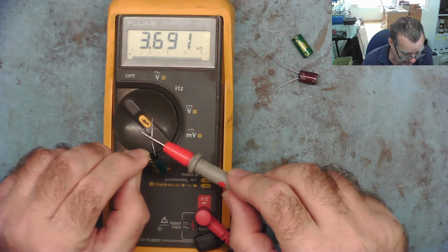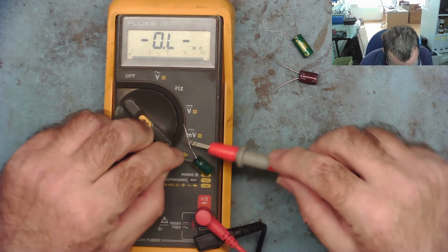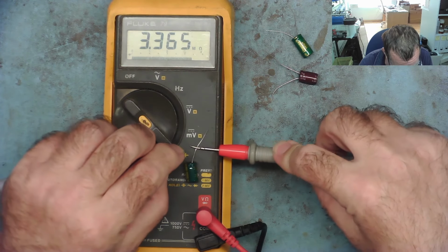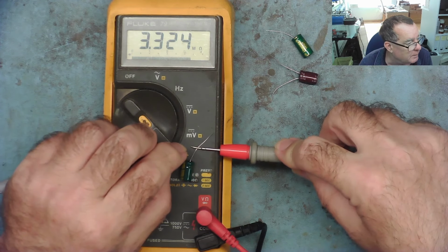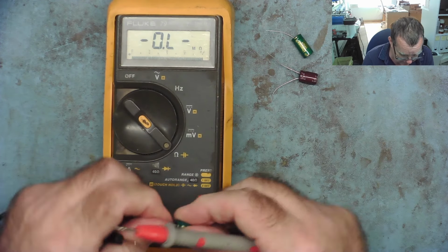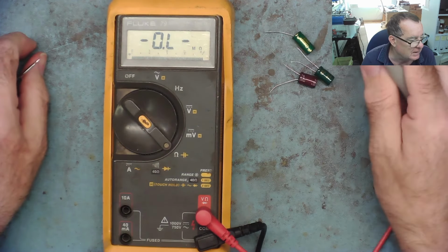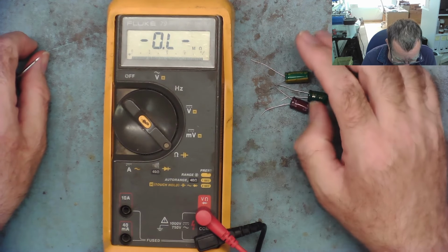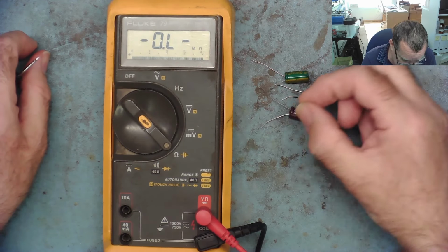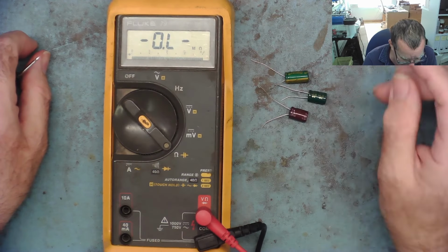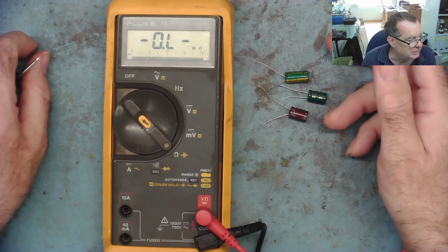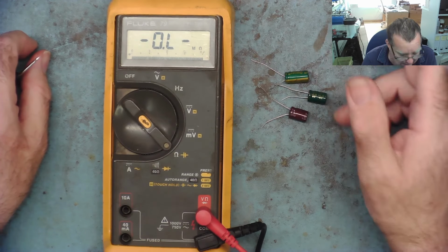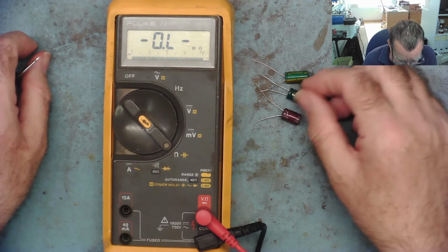now we don't need a negative, yeah? And again, it's climbing up. I'm just going to get a good connection onto it. 3.35 mega ohms, yeah? So, is that resistance the ESR? Well, actually, the answer to that is no, that is not the ESR. What we're seeing is the initial reading, for an instant, is the capacitor charging up, and then after that, we're actually seeing the leakage current.